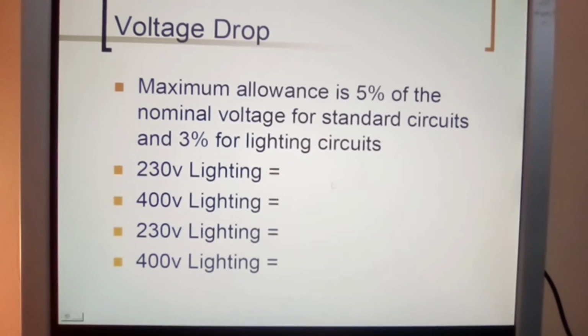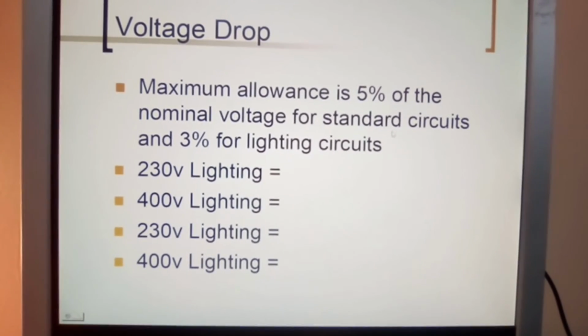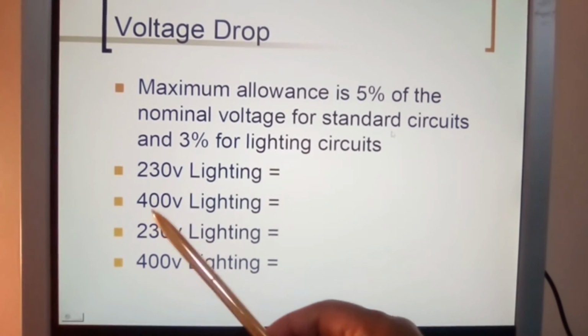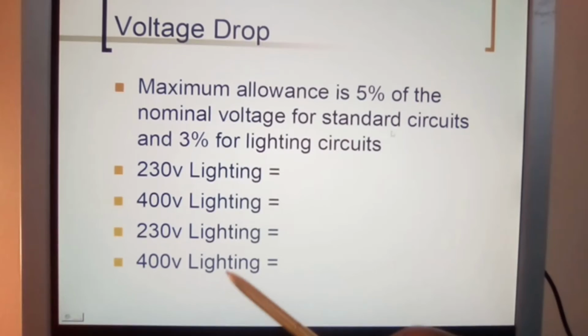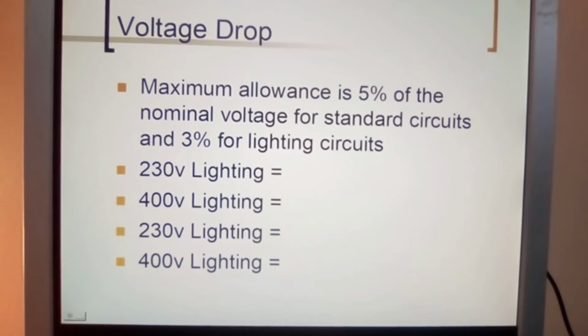They're all lighting circuits in this case. But for this purpose, you need to look at 400 volts at approximately 5% and 230 volts at 3%.